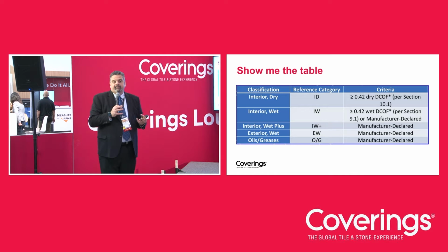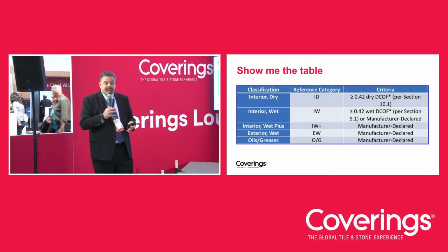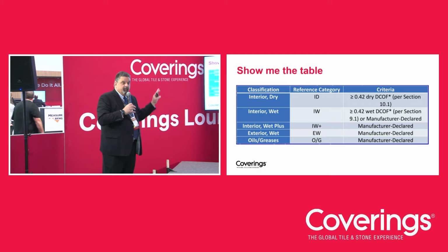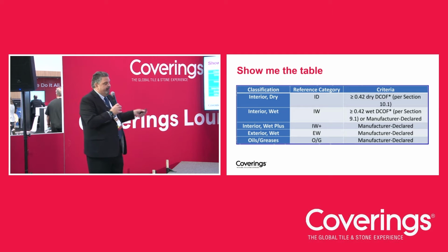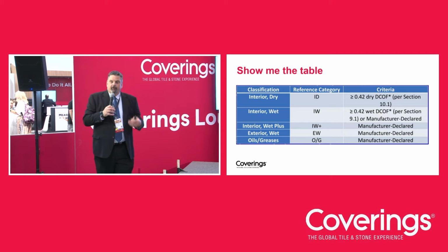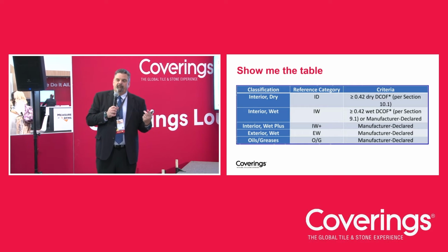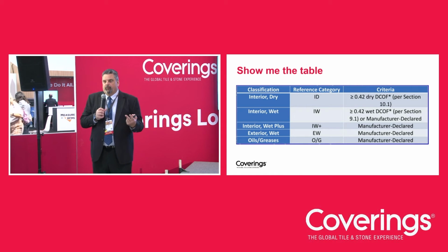So the TCNA gives out the A326.3 standard for measuring it. It tells you how it's measured, and then it gives you the table, and it gives you more information about what's in the table. So with that said, I'm going to go through each of these categories a little later on. But my laser pointer's not pointing, sorry. But you get a feel for the first two are basically what we talked about before. It's either dry and it's less than 0.42, or it's wet and it's greater than 0.42.